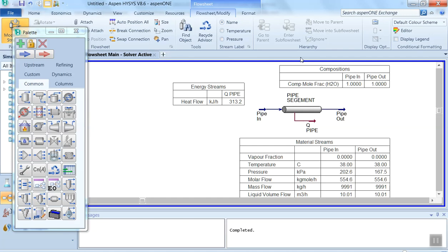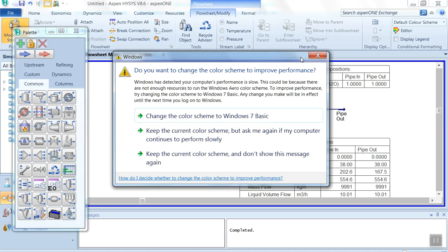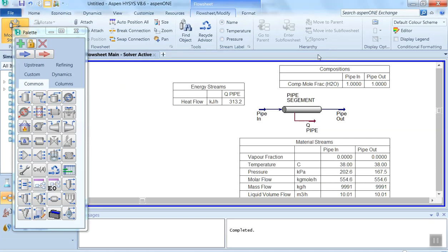In conclusion, proper selection of the pipe segment according to the applications and working environment is very important, especially in the petroleum and petrochemical industry. This is because the pipe segment has to be designed according to the pressure, temperature, viscosity, even the type of flow, and even the chemical properties of the fluid transported through the pipe.